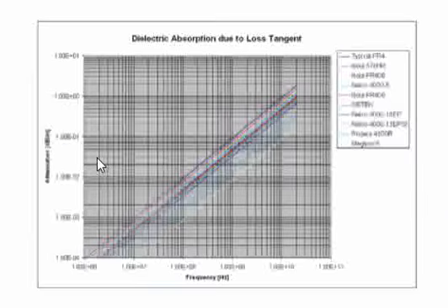The graph we see here is attenuation versus frequency. So you can see here frequency is on the x-axis, attenuation, which is dB per inch on a PCB material, is on the y-axis, and frequency versus attenuation is drawn for different dielectric materials. This is from the Intel website, where different materials' attenuations have been mentioned. We can see here the Megtron 6 material, which is having a frequency versus attenuation graph,